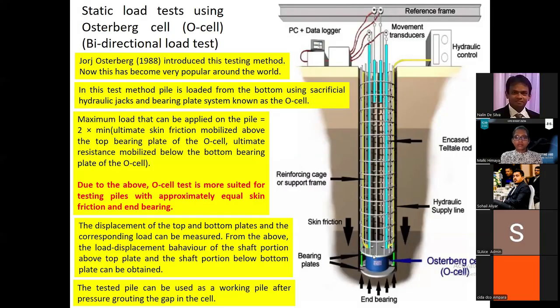But this is not very popular for end bearing piles, because in Sri Lanka we have mostly end bearing piles. With end bearing piles, the end bearing is much larger than the skin friction. Therefore, this has limited applicability in this type of subsurface conditions. Okay, O-cell tests.